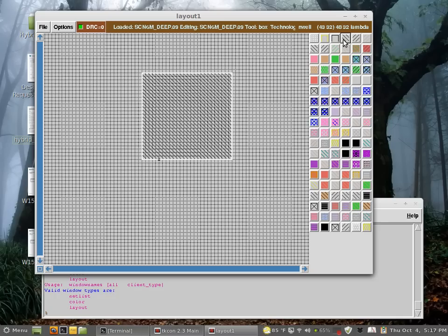Now most laptops don't have a middle click. I have a middle click on my laptop. Middle click is that middle button in the mouse. If you go to the Swamp Lab, the mice there have a middle click on them. So you middle click on the color here, on the layer, and it fills the rectangle with that layer. That's basically how you fill it.